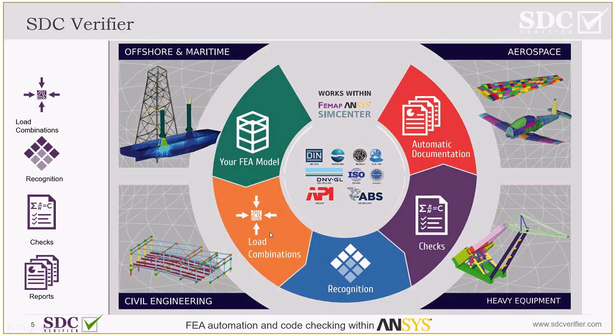This is the workflow cycle with SDC Verifier. We take your finite element model, do the combination of loading, do the recognition of structural members, then the checks, and then the automatic documentation. Everything is stored and template based. So if you already have the report and need to do an update, you don't need to repeat all the steps. You just update your model and regenerate the documentation.